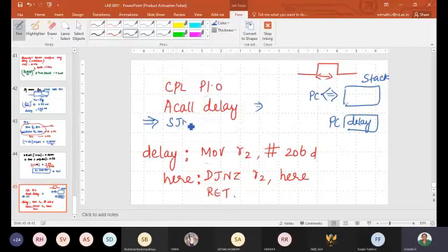Let me use an unconditional jump, SJMP, short jump, and let me use a label such as square, whatever. I need to go ahead with this label. So this is how the program is. The program ends here. Once that is done, you can have an END statement, and you can use even your assembler directive ORG to start your program from this address. So let me use ORG.